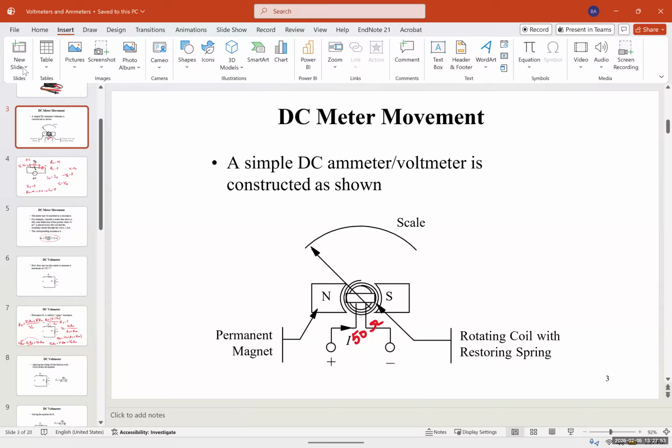Okay. So this is the reason behind why we switch the terminals when we go from a voltmeter to the ammeter. As you may remember, on a digital multimeter or any multimeter, you can see that it has a common point and a voltage or a current point. So one is voltage, one is current. Even some of them have 2 voltage points and 1 current. When you connect to them, you're connecting to an internal resistor. And that's the reason if you forget to switch and go from an ammeter to a voltmeter, you're going to immediately damage or destroy the voltmeter.